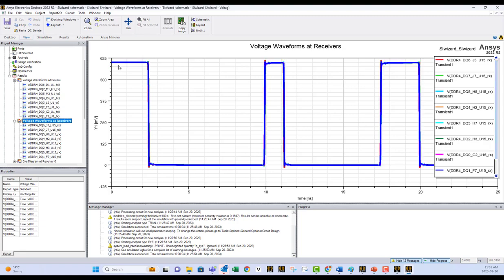Now notice that the voltage here is half what we asked for. We asked for 1.2. The reason why is because the signal acts as a power divider. So it divides the voltage into half. So whatever voltage you need to see in the output, you need to double it in the setup. So if I want to see 1.2 volt, then I have to put 2.4 volt.